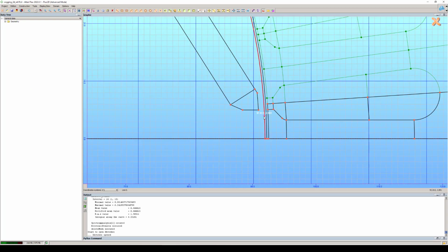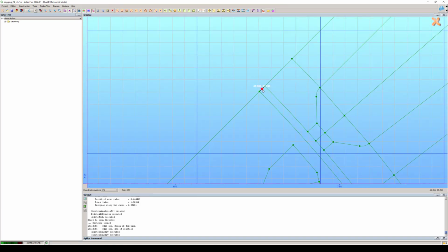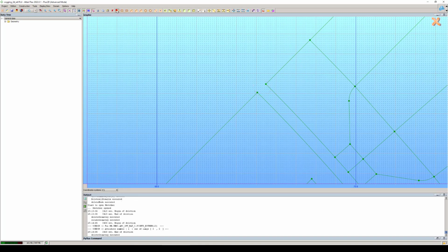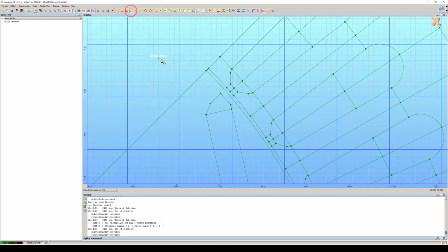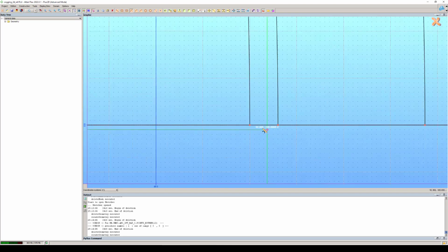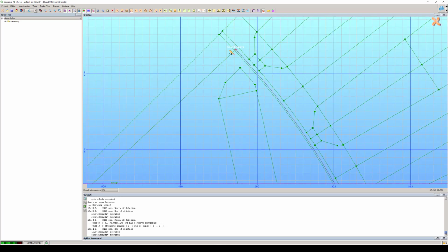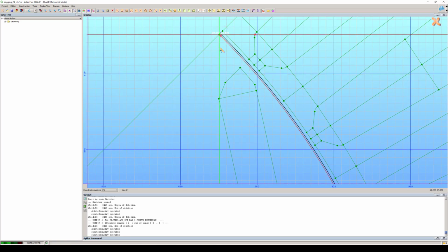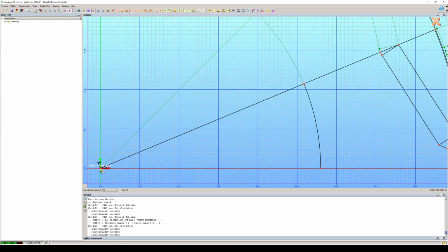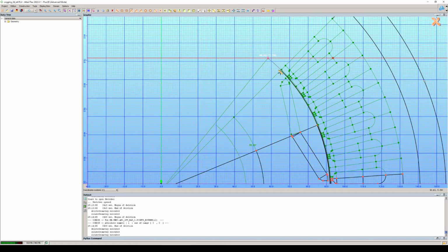So if I go in the sketcher and I remove this one, I just replace it by a line for now. And I will go here and remove as well this point, just make it a single line. And now I will draw one more layer in the air gap. So I'll try to put it like 1/3 of the thickness. So I draw a new arc. I start somewhere here, let's say here, up to the other side. Okay, and then another arc. Starting here and then going up this way.